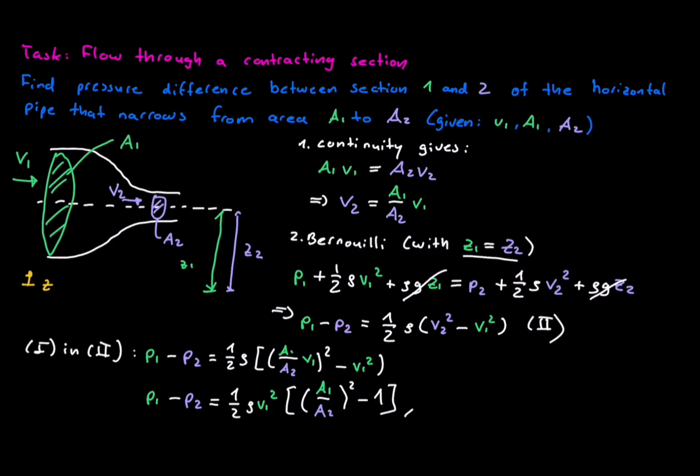So as the pipe narrows, velocity rises and pressure drops. Pressure energy turns into kinetic energy, exactly what happens in a nozzle or a venturi tube.